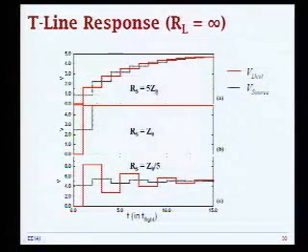And this was because of impedance mismatch. So you have very long rise time determined by this time of flight back and forth. Now, in this case, you have perfectly matched scenario where you basically inject 1/2 of the waveform initially, then the other half comes back from the reflection, and you immediately establish the final value.